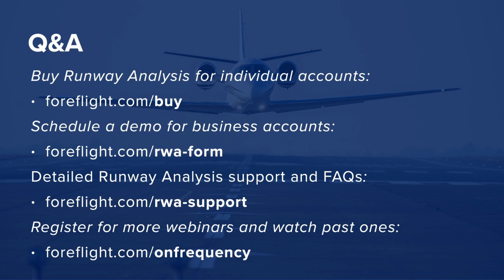Sometimes that's not possible to do. If there's terrain obstacles that are conflicting with single engine performance, then we have to take the aircraft off of the published procedure much sooner in our own EOP than we would in other cases. But the short answer is, if it's advantageous from a terrain and obstacle standpoint, we're going to leave you, at least in the beginning of the procedure, on the published procedure.